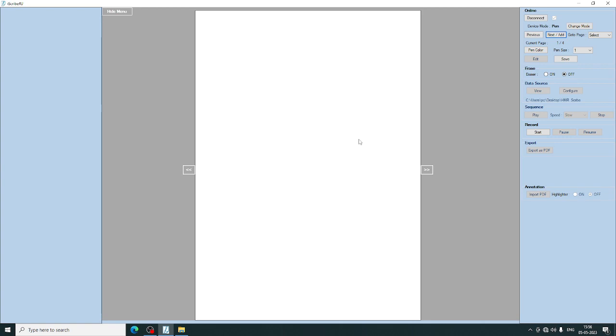Common gate containing the same circuit. This is the source resistance, and this is the input signal, V in, that we are giving to the source terminal through resistance Rs. This is VB and this is V out, RD and VDD. Here we know the output impedance is very large.